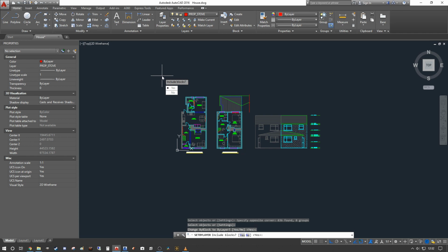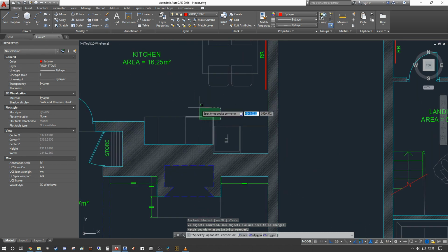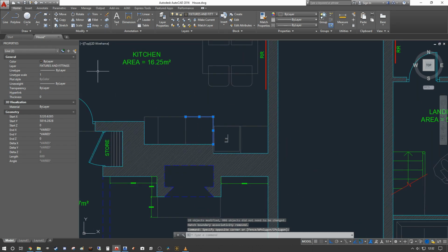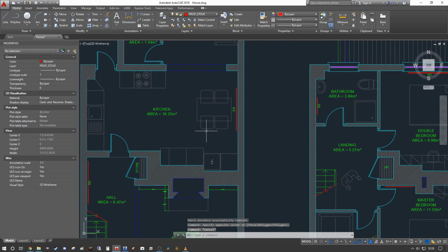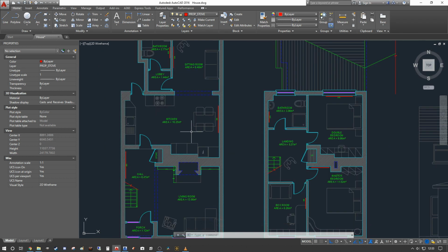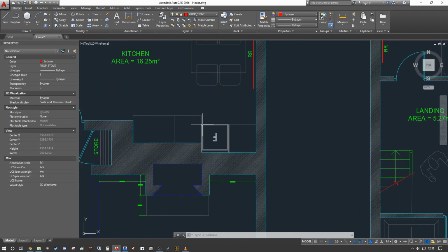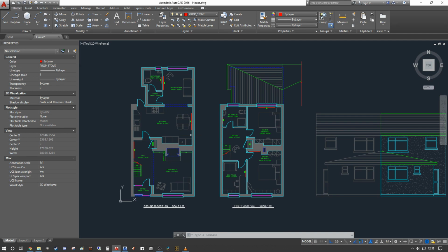Do you want to include the blocks? Yes. And as you can see, our casework has changed back to color by layer. This is really useful if you're getting CAD data in from external design stakeholders, because you may not be familiar with their layering convention or how they colorize the drawing either. So it just gives you an extra level of control in the Revit environment.